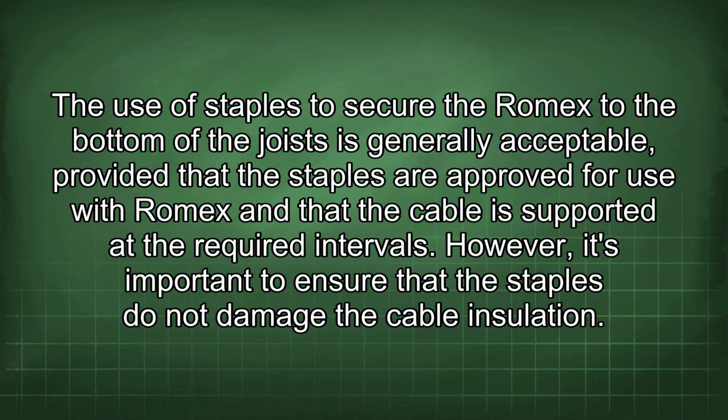The use of staples to secure the Romex to the bottom of the joist is generally acceptable, provided that the staples are approved for use with Romex and that the cable is supported at the required intervals. However, it's important to ensure that the staples do not damage the cable insulation.